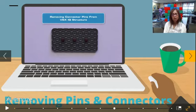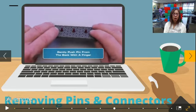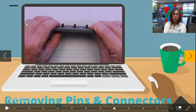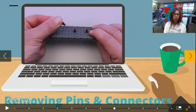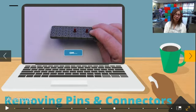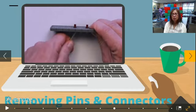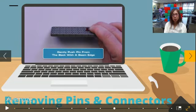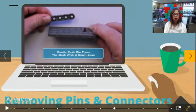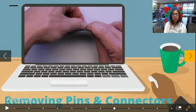You can remove it by flipping the graham cracker piece over, and then you can stick your thumb underneath and kind of pop that pin out a little bit. So when you do stuff like this, you need to make sure you put a hand or a cover on the other side so that pin doesn't go flying across the room or in someone's eye. Another idea that works a little bit better for me is to use that silver shaft and to approach it from the underside again and poke that out. You can also use other building components that have a corner or a beveled edge, and you just do the same thing. Poke it out from the underside and pull it out.